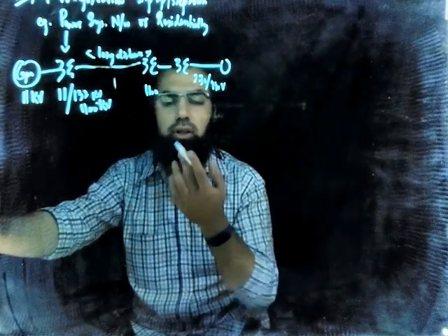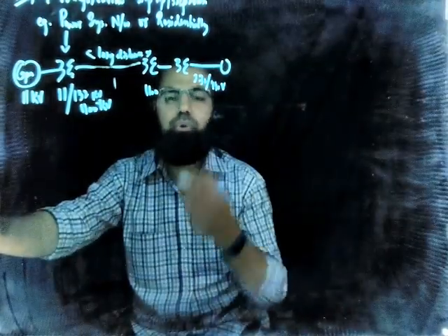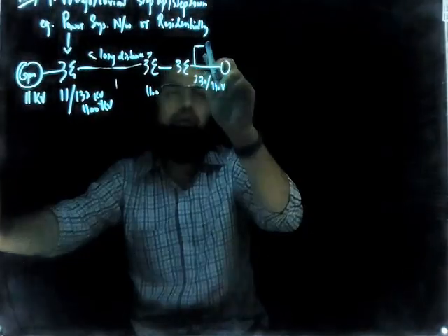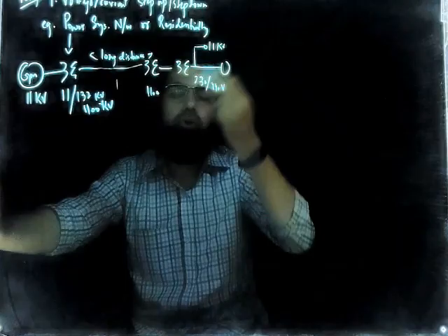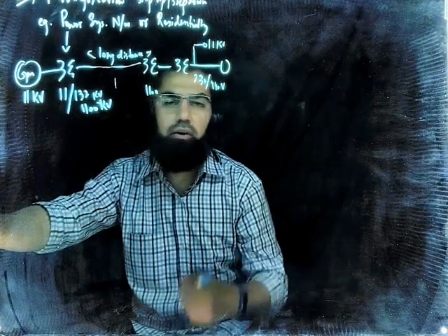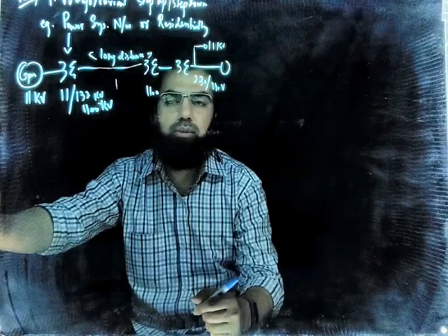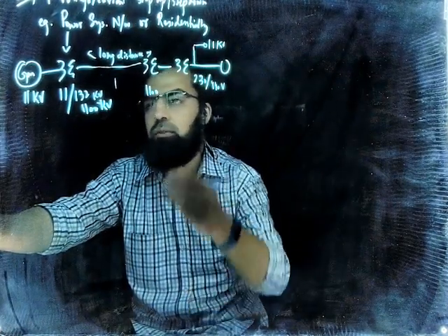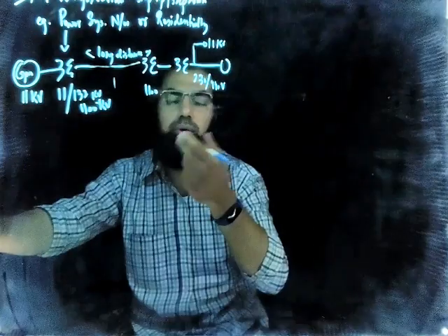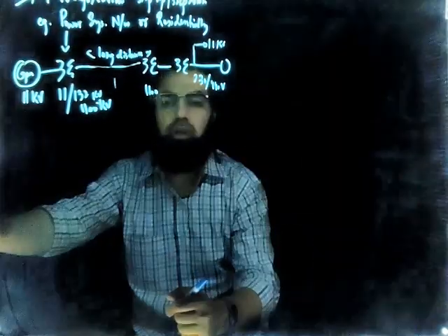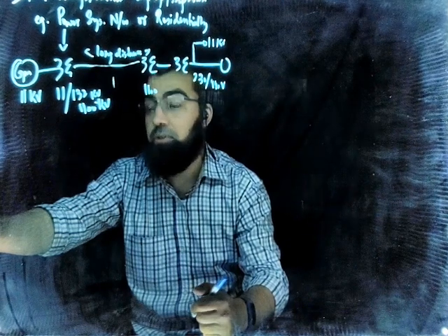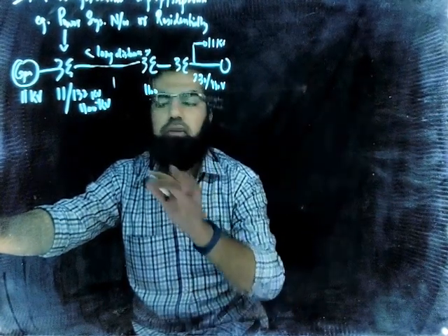So using a series of transformers, from 11 kV to 230 volts, that's actually available to a consumer. If it's going to industrial purposes, they directly require 11 kV, so for them it will be reduced to 11 kV. If you get a chance to visit the substation of your campus, NIT Srinagar, you will see that the voltage that's actually received is 11 kV, and using the local distribution transformers, we are able to reduce that voltage to 440 or 230 volts for single phase and three phase purposes. So this is your power system network.